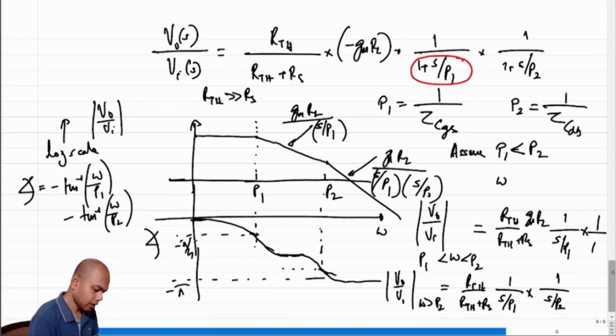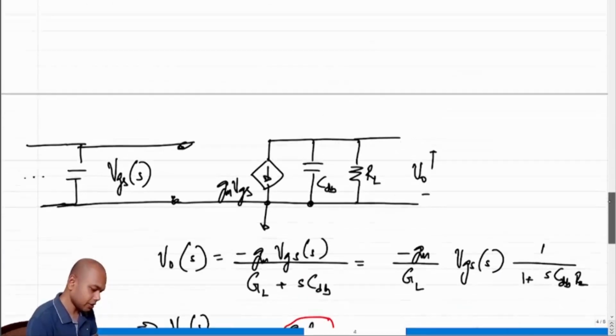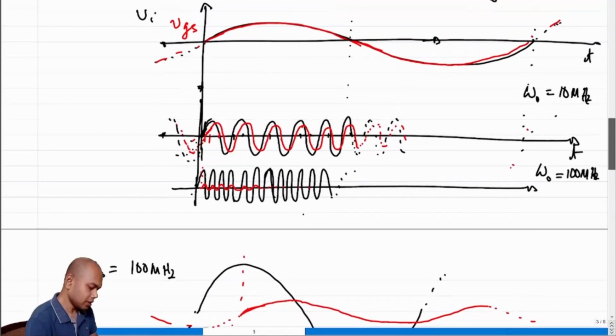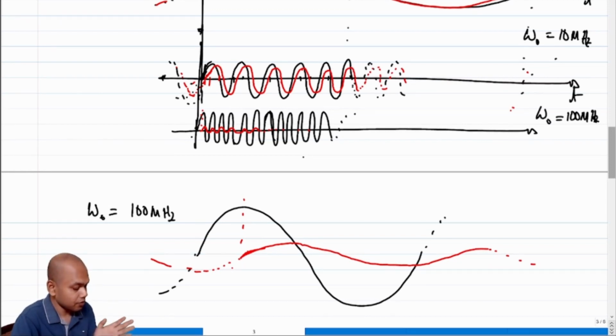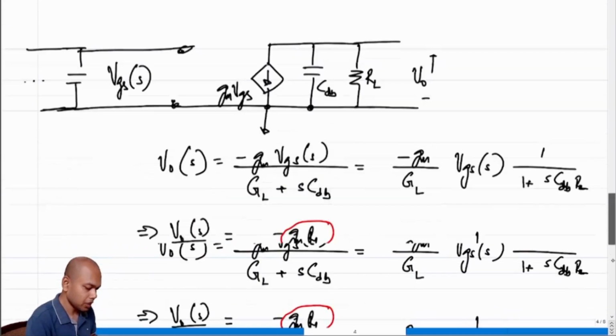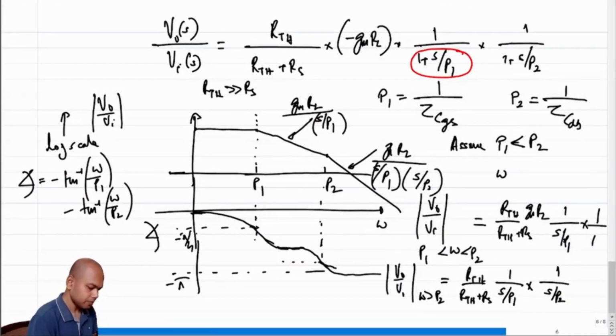And what impact will that have on our transient response? Just that you will see that the maximum phase delay that we could have had at very high frequencies would have been only 90 degrees, but now we can have 180 degrees maximum phase delay, which means there can be a half cycle delay of the input at max at very high frequencies. What is very high frequency? In this case, it is at frequencies much higher than P2, right? Okay.